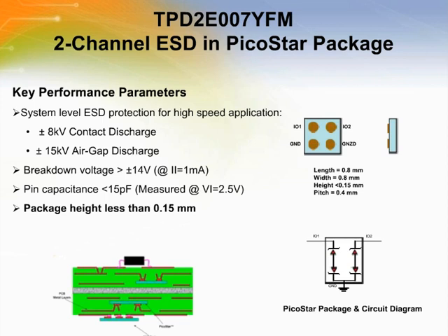The PicoStar package is intended to be embedded inside the printed circuit board, which saves board space in portable applications. This device exceeds the IEC 61000-4-2 ESD protection and suitable to provide system-level ESD protection for the valuable internal ICs while placed near the connector.